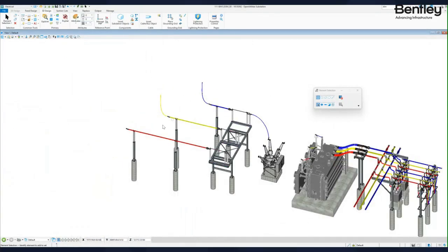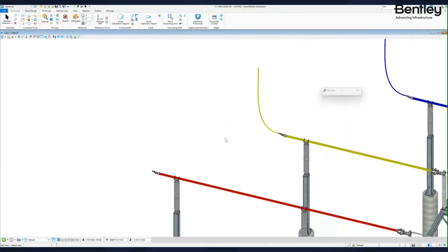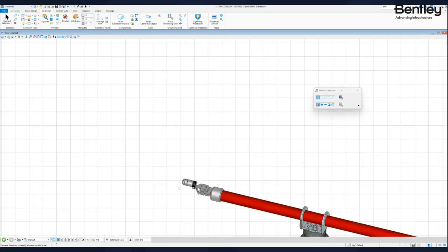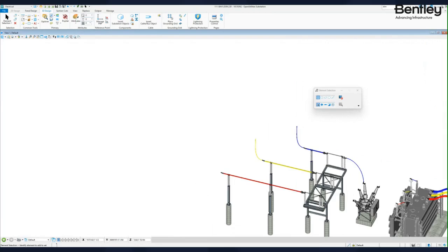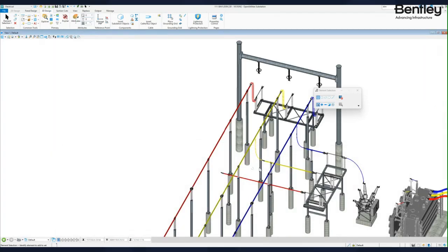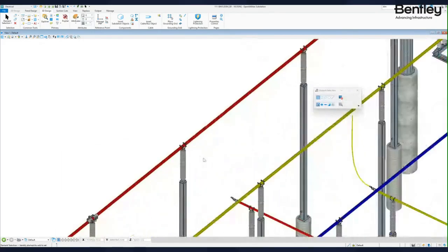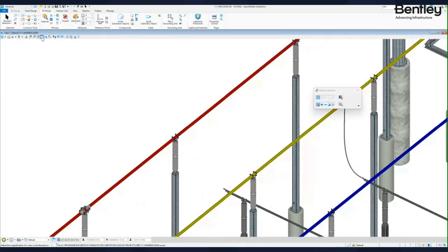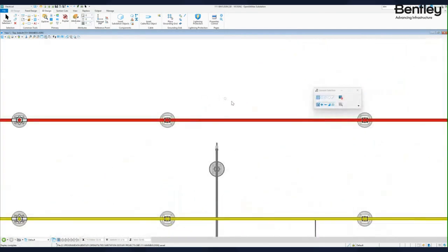Okay. What about if I'm missing something here, that I have my cable, here I may have my clamp. I can just simply go and reference the main bus maybe and see how I will connect to it. And I will just simply only do this portion of the drawing. I can simply click, activate the reference. That means that I'm activating the different file with the collaboration with my already existing. I just can go on the top,